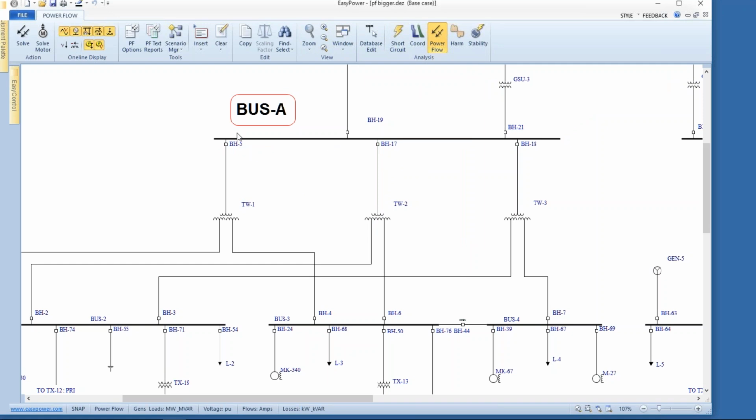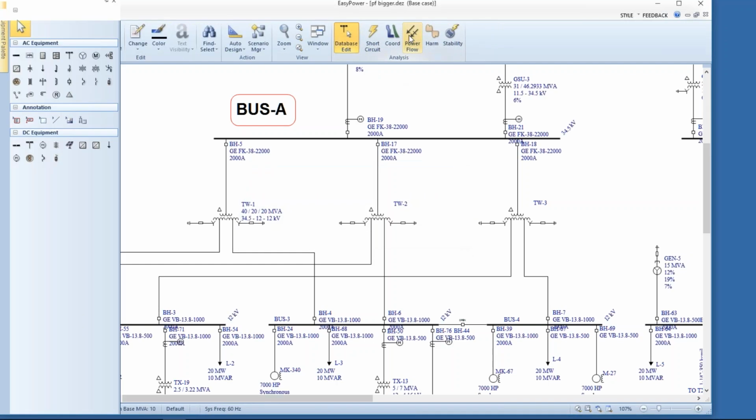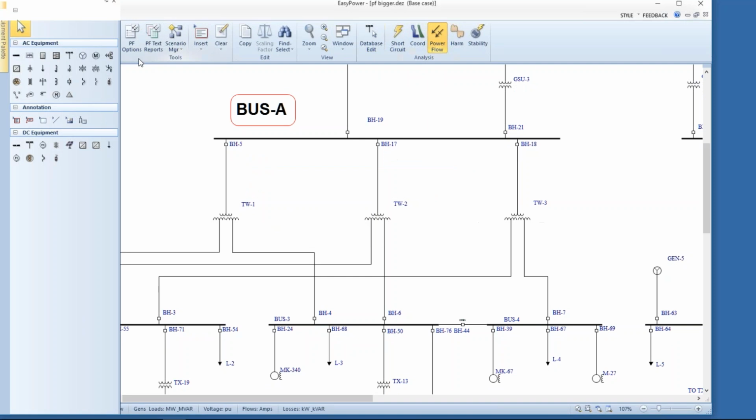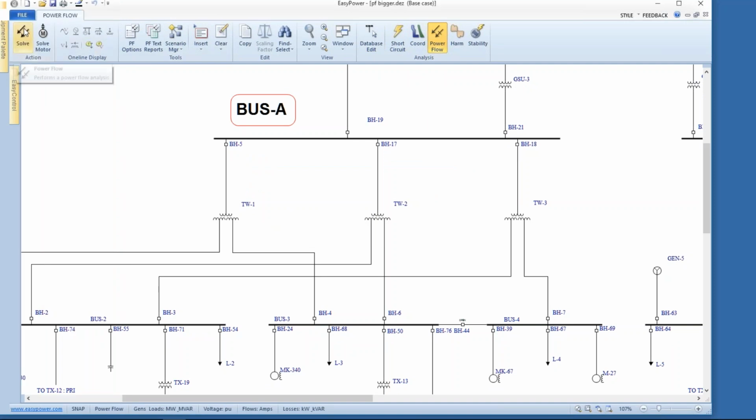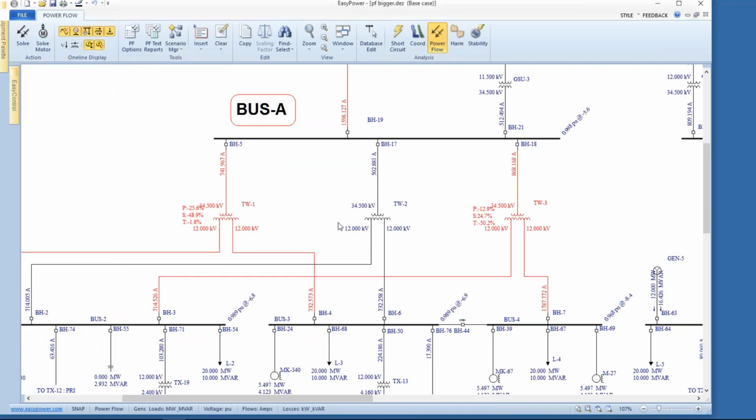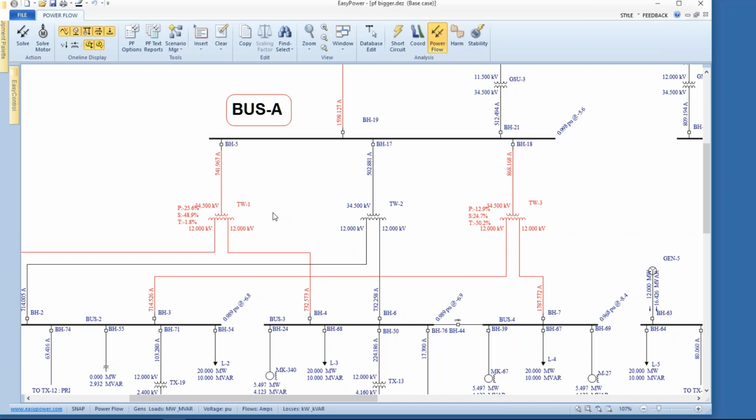Now the point being is that this is a breaker that I had open, and so a logical progression would be, if I go back and try to open this again now with that breaker closed, if my PowerFlow solution now resolves, clearly that was the source of my problems. And as soon as I do that, I can see I have some control warnings that make me realize trying to resolve the problem with that breaker open is not a good idea.